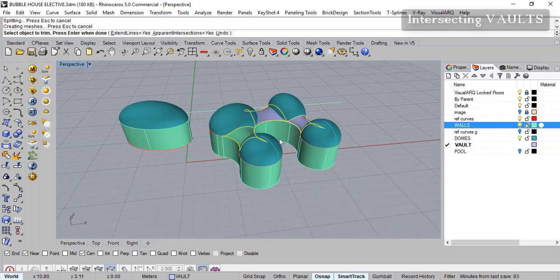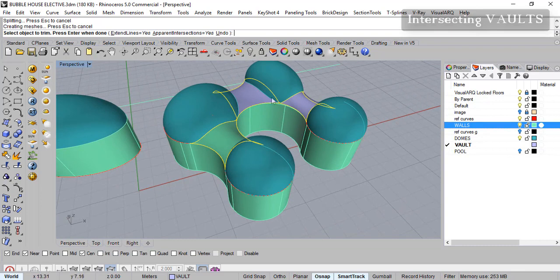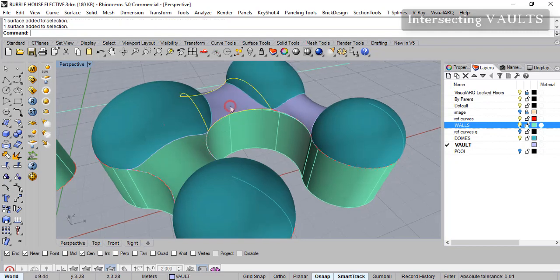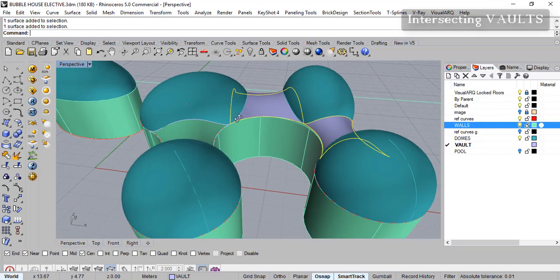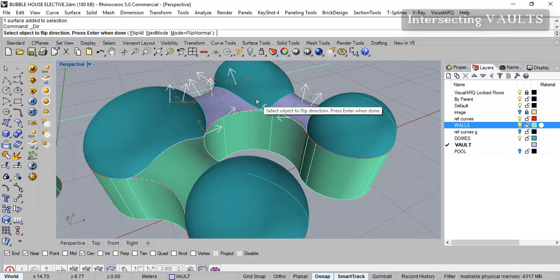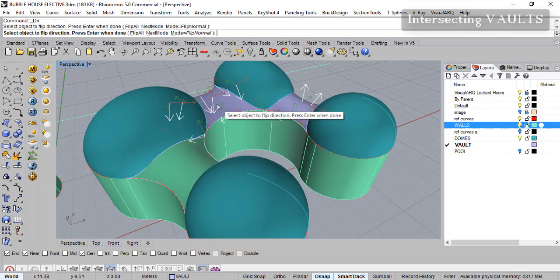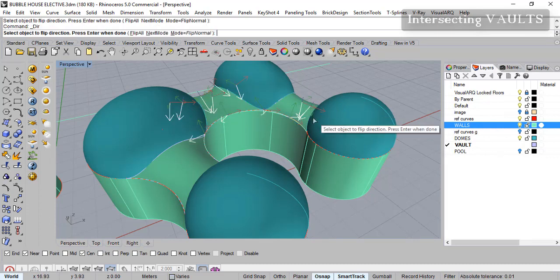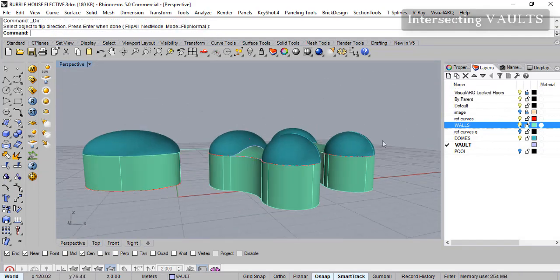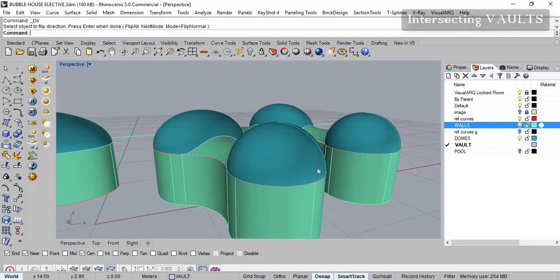And put the walls, these walls are drawn in the walls layer. Only thing, there is some change of sides here. So here you can see the backside on top. So what we need to do is select this. If there are some backsides seen like this on top, select those objects and go to analyze, and then it will show you some arrows. So then you just have to click on the surfaces again till the arrow points down and say enter. So then it will reverse the directions of this.